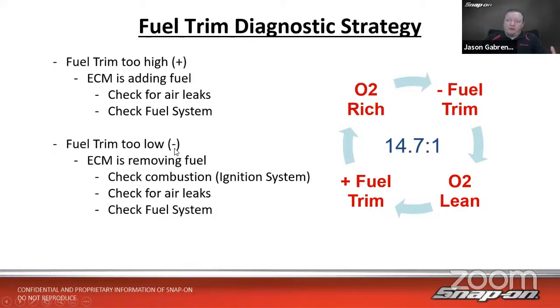If fuel trim is too low, it's pulling negative. That means it's too rich. All right, so ECM is trying to remove fuel. It's too rich. Maybe check combustion. The ignition system's not performing properly. Also check for air leaks.